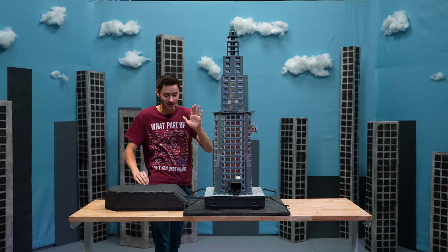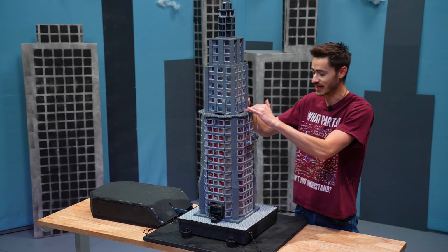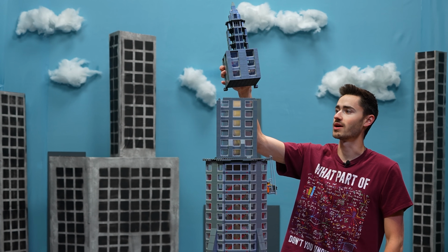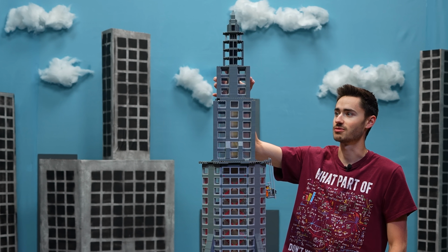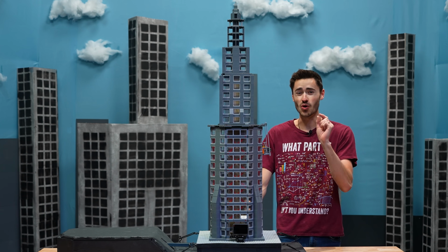So as you can see, this definitely works way better than it did without any reinforcing at all. I think the shear wall definitely helped down for this bottom section because it seems a lot sturdier. And then up towards the top here, there were honestly only 4 studs of connection, so that wasn't the smartest thing. But this thing definitely worked out a lot better than with nothing at all. And we were pushing that to almost its max.